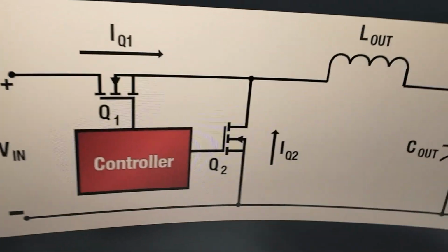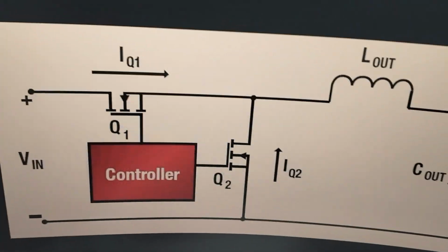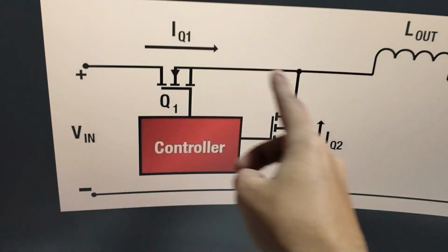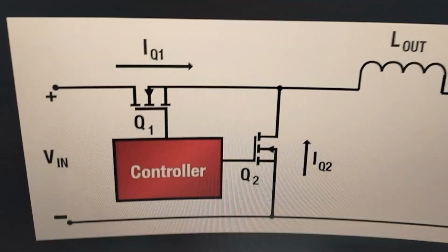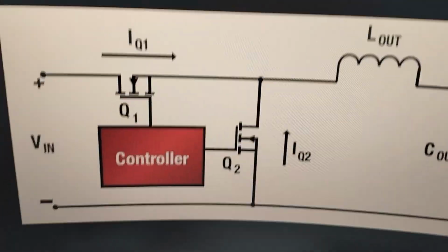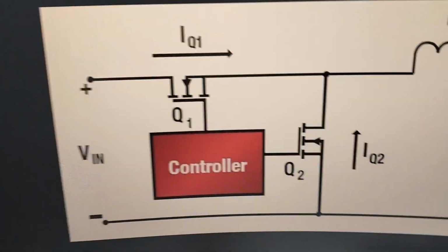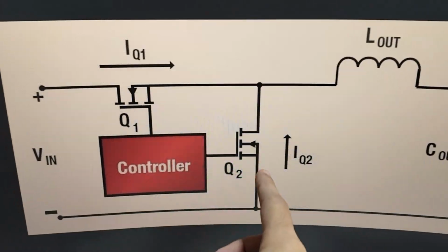And we know that in a half bridge, both the switches can never be on at the same time, because obviously if you have both on at the same time, it's directly going to get shorted, and you're going to have a big short circuit current flowing, and possibly blow up your MOSFET and all of that. So that is what we call a shoot through. It's called a shoot through condition.